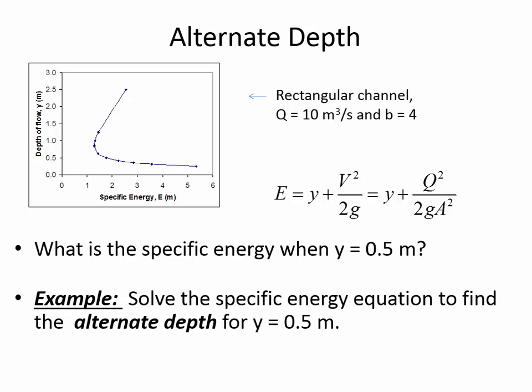Say it again. Oh, very good. Yeah, I hadn't even thought of it that way, but one of them is the supercritical depth. One is the subcritical depth associated with the same amount of energy. That's right. So this is the subcritical depth, and this is the supercritical depth associated with the same energy level.